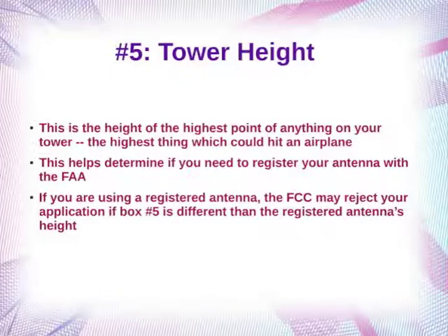Tower height, question number 5. Pretty self-explanatory. The thing to remember here is if you put your antenna on the middle of a tower or the middle of a telephone pole, for example, this is the height of the top of the telephone pole. If you put your antenna on top of a telephone pole, then that makes the structure higher, so in that case you have to measure to the top of the antenna. It's really, what's the highest thing that could hit an airplane? That's what the FAA cares about, and I think that's the easiest way to think about tower height.